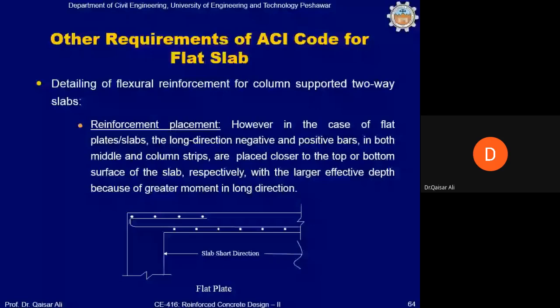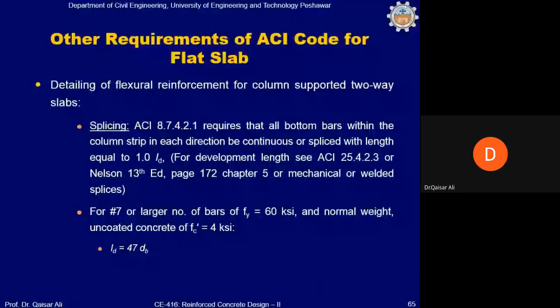Splicing. Splicing will be frequently required, which you know that lapping is the general method of splicing. Lapping by splicing is allowed in the slabs, but it shall be avoided in the critical location. For positive reinforcement, the lapping shall be avoided in the midspan of the slab, and the lapping shall be carried towards the